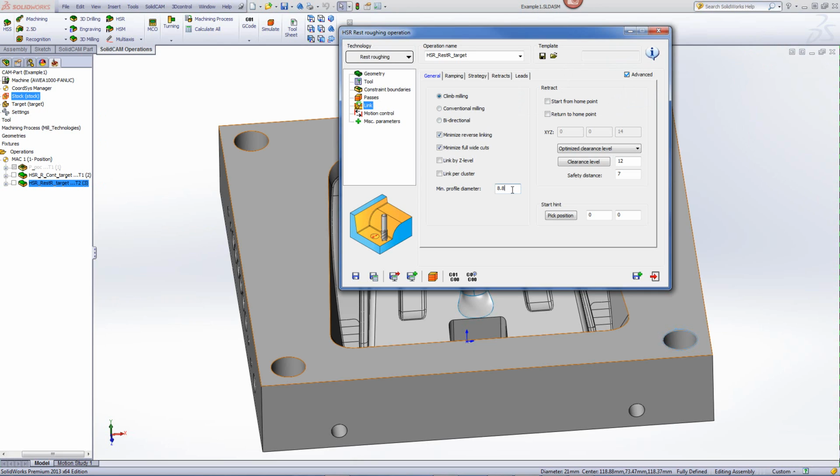The tool that I'm using in this particular case is a 12 millimeter bullnose tool with 12 millimeters on top and 8 millimeters on bottom. If I take this value, 8.8, and add it to my 12 millimeter diameter, that would give me a total of 20.8 millimeters. The hole itself is 21 millimeters. This came out now to 20.8. However, we still have an offset of 0.5 millimeters.